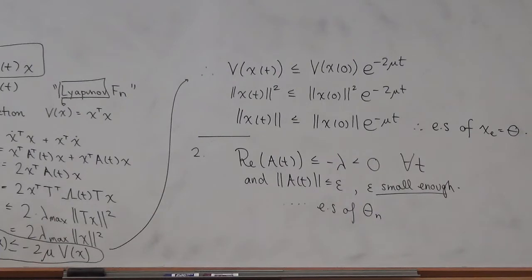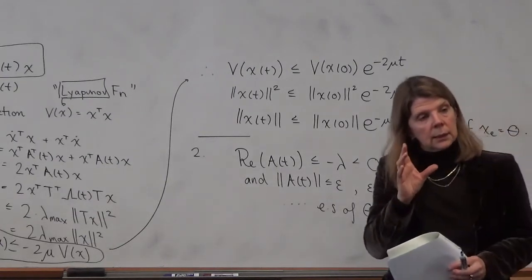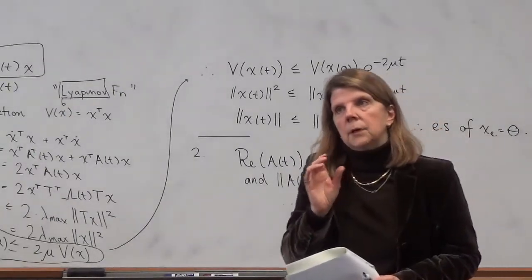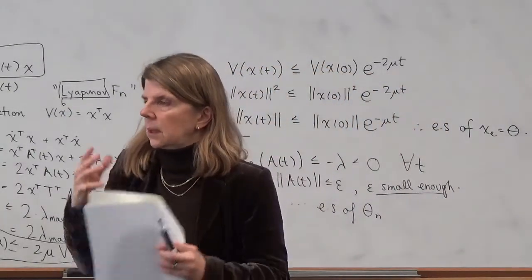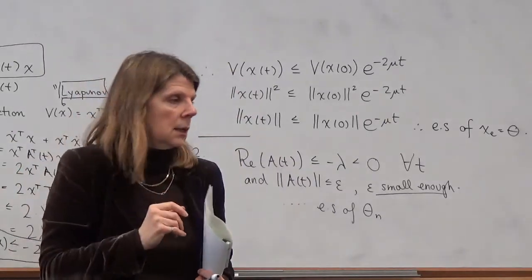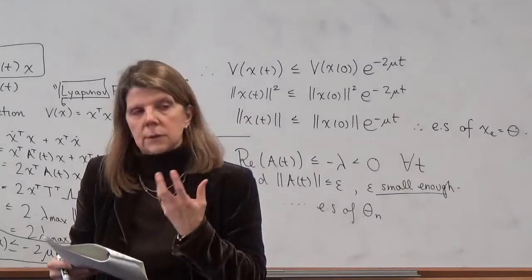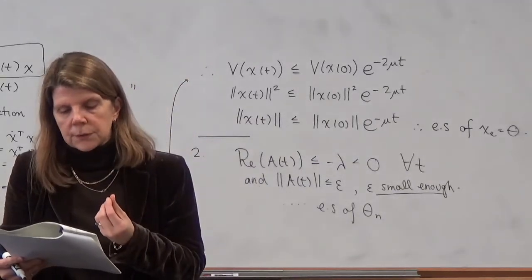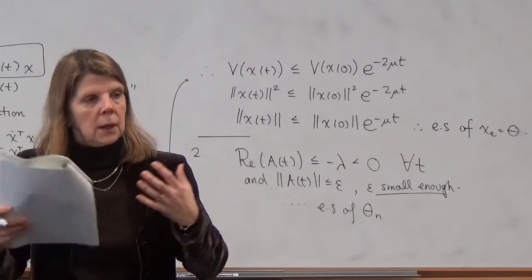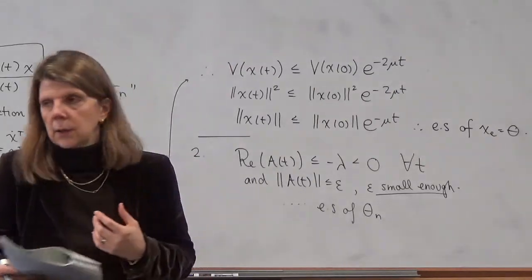Maybe not just for direct proofs of stability for linear time invariant systems, but more as a technique for proving stability of more general systems. Perhaps you have a nonlinear system and you do a Jacobian linearization, so you look at that linear component. Lyapunov theory allows you to prove stability about the nonlinear system locally, based on the stability of the linearization. And so things like that. So it is something that, coupled with different kinds of systems, is a very powerful technique.